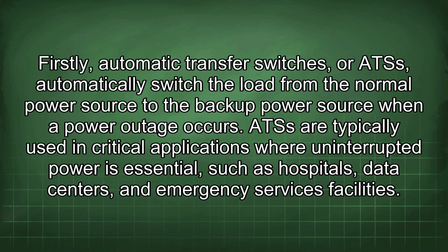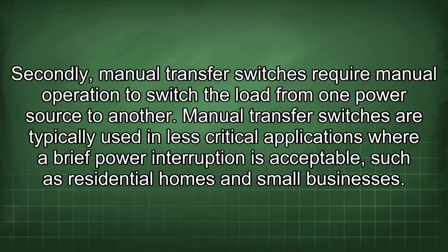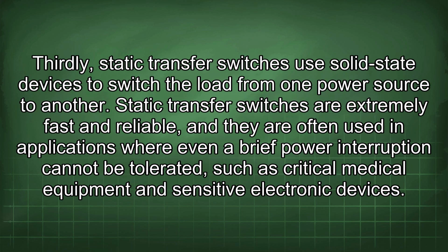ATSs are typically used in critical applications where uninterrupted power is essential, such as hospitals, data centers, and emergency services facilities. Secondly, manual transfer switches require manual operation to switch the load from one power source to another. Manual transfer switches are typically used in less critical applications where a brief power interruption is acceptable, such as residential homes and small businesses.